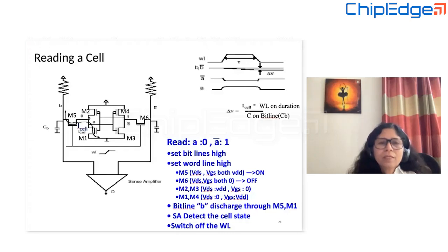But as far as this PMOS is concerned, I can say that this PMOS becoming stronger makes the SNM poorer, because when this zero starts to become one, if this PMOS is stronger, it reads it as a one. So if you have higher voltage, this PMOS will be stronger, and that would make the SNM bad. But other parameters, nowadays sub-threshold nodes are posing different kinds of challenges. So it's hard to say one particular PVT. Sometimes there are several PVTs where SNM needs to be verified.